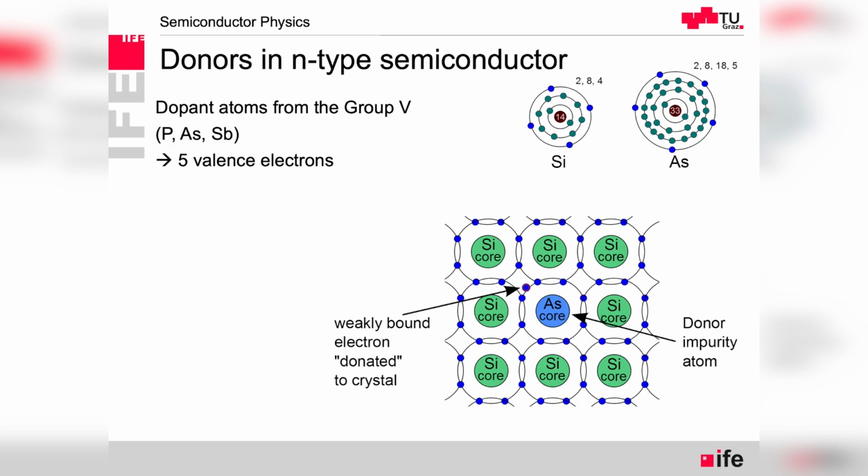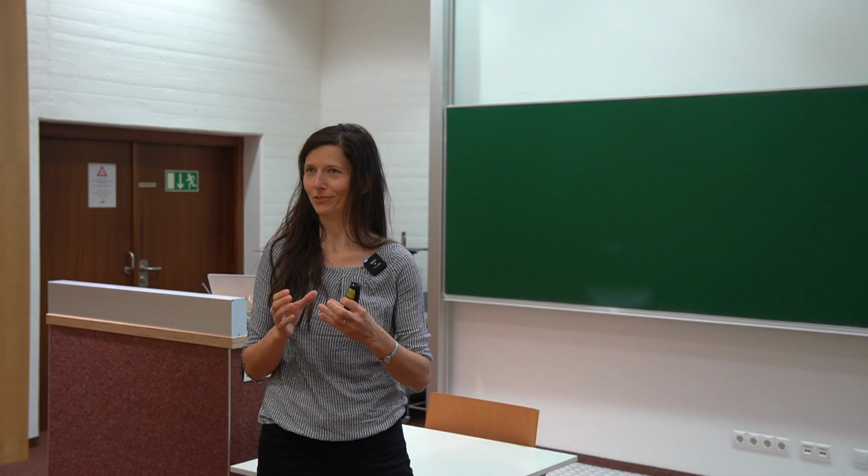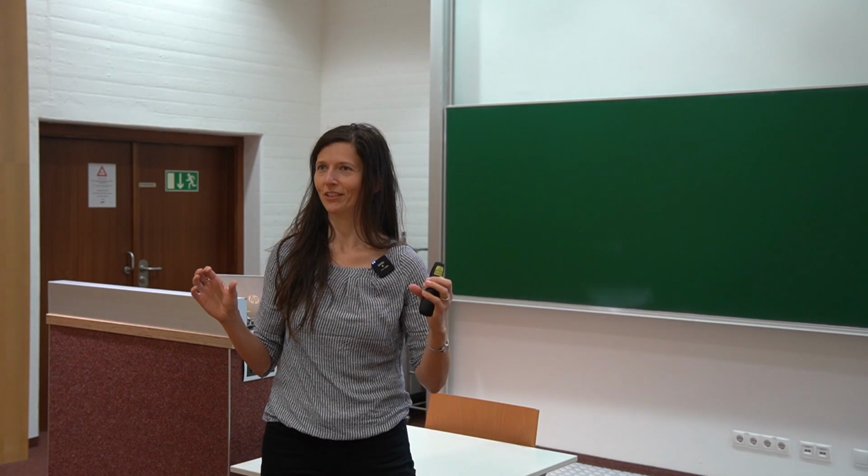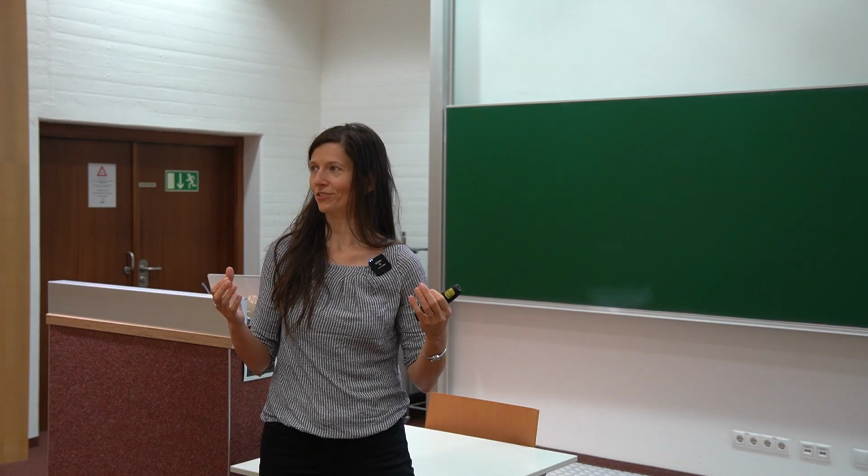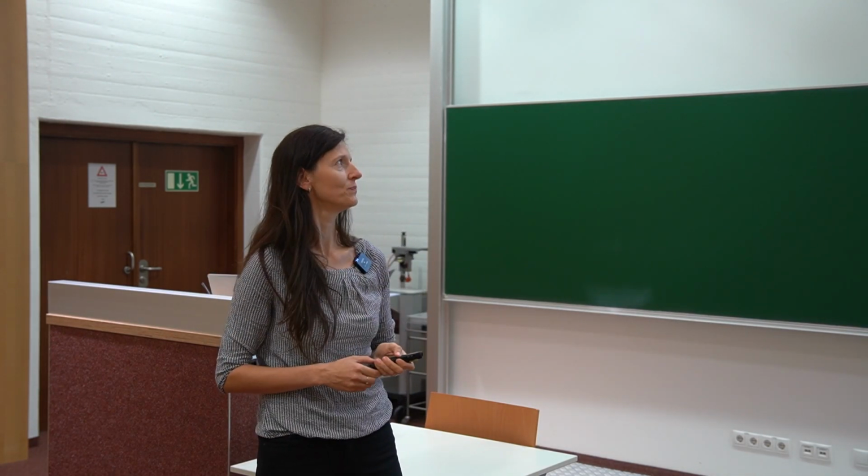In addition to arsenic, we can also use other atoms which have 5 valence electrons. And like that, we have the n-type semiconductor. For n-type MOSFETs, actually for both n-type and p-type MOSFETs, we have n-type and p-type doping, because we will have different doping on the drain and source, and different at the bulk, which is just the difference in the charge carrier concentration.